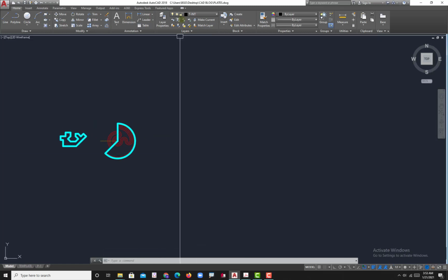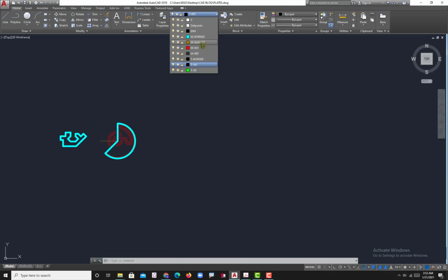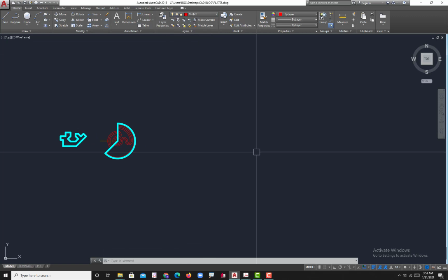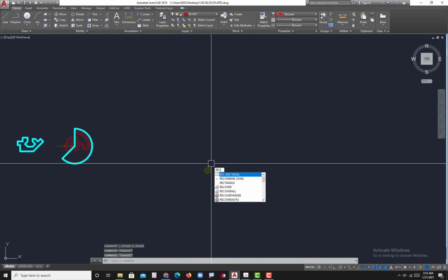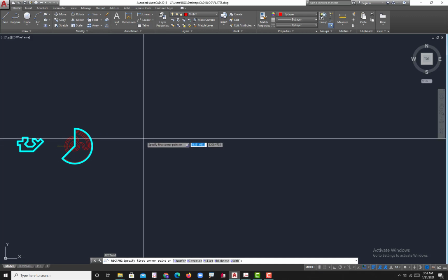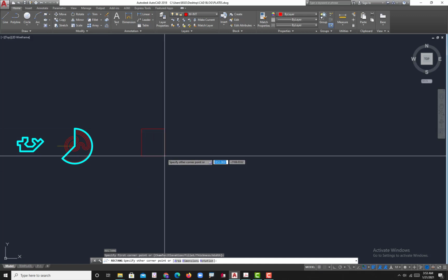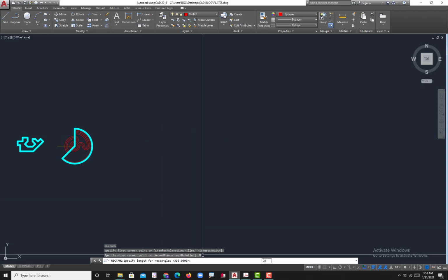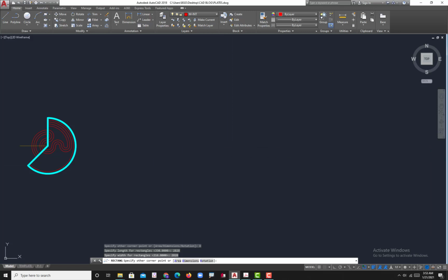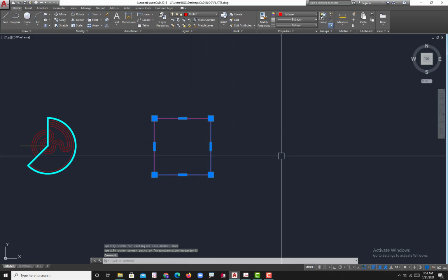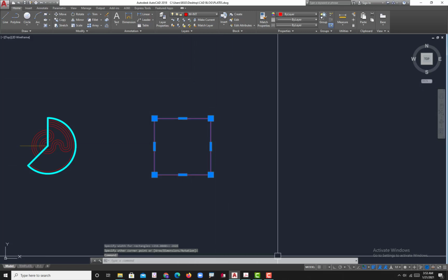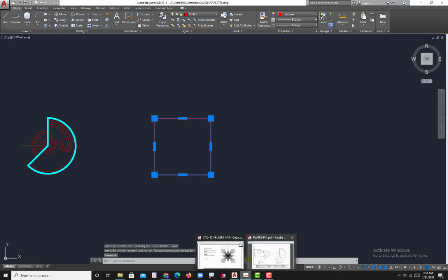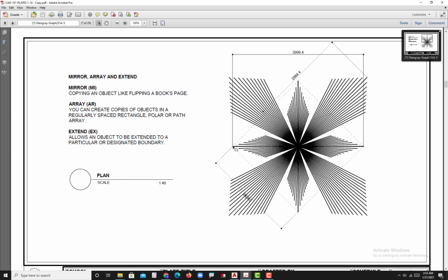Okay, so you go first with the intermediate lines again, then rectangle, enter. Okay, specify first corner, then I have the option there for D. Just click on that one, then 2828, enter by 2828. Okay, and then select and then rotate, no? So this one is under a 45 degree, no? So you rotate this object at a 45 degree.